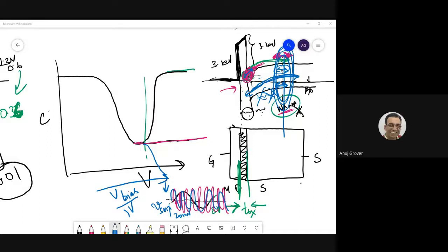Sir, yes, Gaurav. With an AC signal at low frequency, will the MOS capacitor continuously toggle between accumulation and inversion mode? No, what did I just tell you? What you're talking about is small signal movement. We said the bias voltage is 1 volt, but it is only moving by plus minus. So it is only moving between 980 millivolts to 1020 millivolts. So that doesn't guarantee an accumulation region.